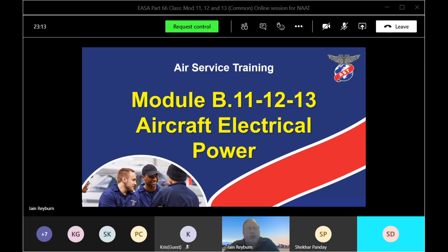The third one is my voltage protection. And we're going to protect between over voltage and under voltage. Over voltage, approximately when 33 volts starts to come out of my TRU, I need to shut it down. I really do need to shut it down, putting too much voltage into the DC system. So we will actually remove the supply from the TRU when it gets too high. But we've also got under volts protection, and it's approximately when we get 22 volts coming out. If I've got 22 coming out of the TRU and 28 on the bus, we're going to end up having reverse current. So again, we will shut down the TRU when the output drops below approximately 22 volts.